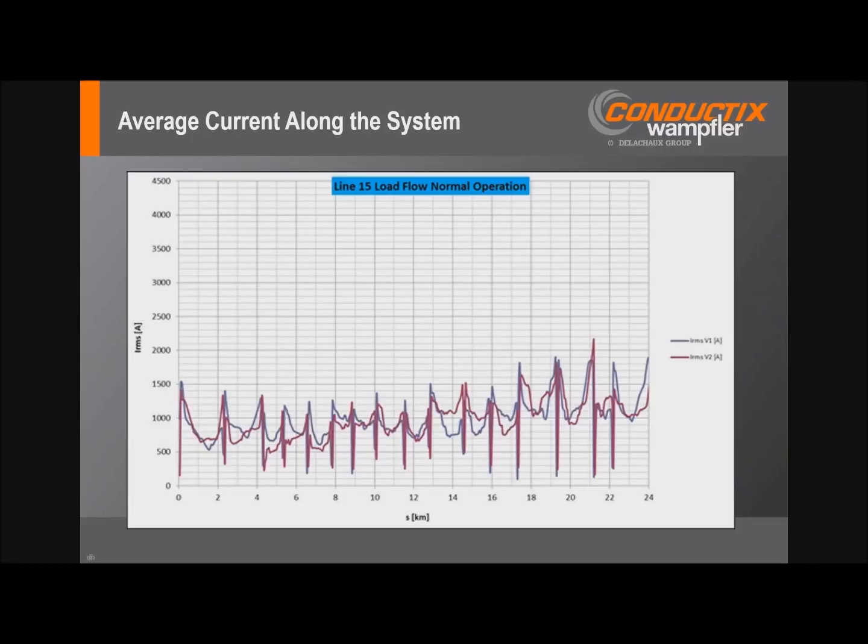So recommended maintenance period. Well, for collector shoes, that really kind of depends. It's kind of like they say with your tires on your car. Actual mileage may vary, so it depends on the nature of the system. Initially with a new system, I'd probably be checking it every couple of weeks until things settle down. But again, looking at typically the key problem areas. Check the anchors, make sure they're holding.